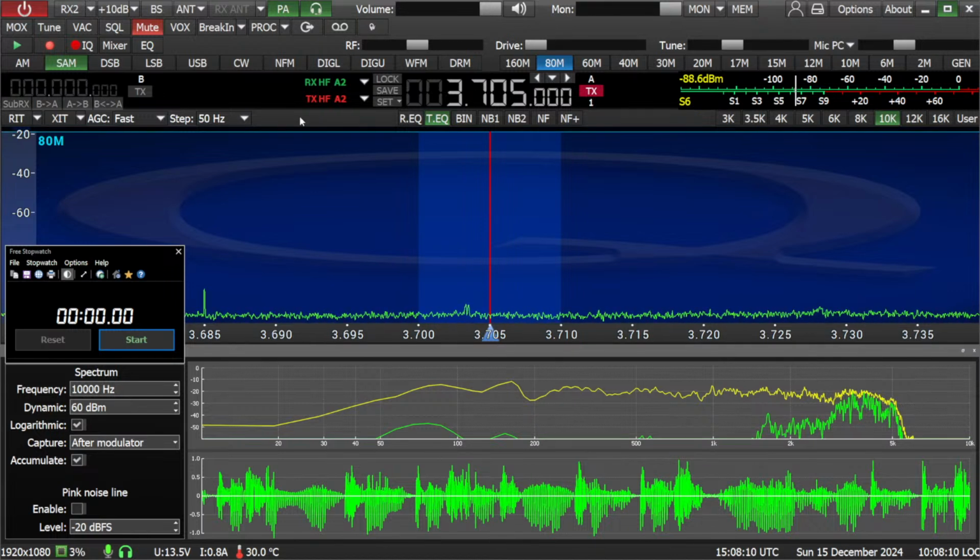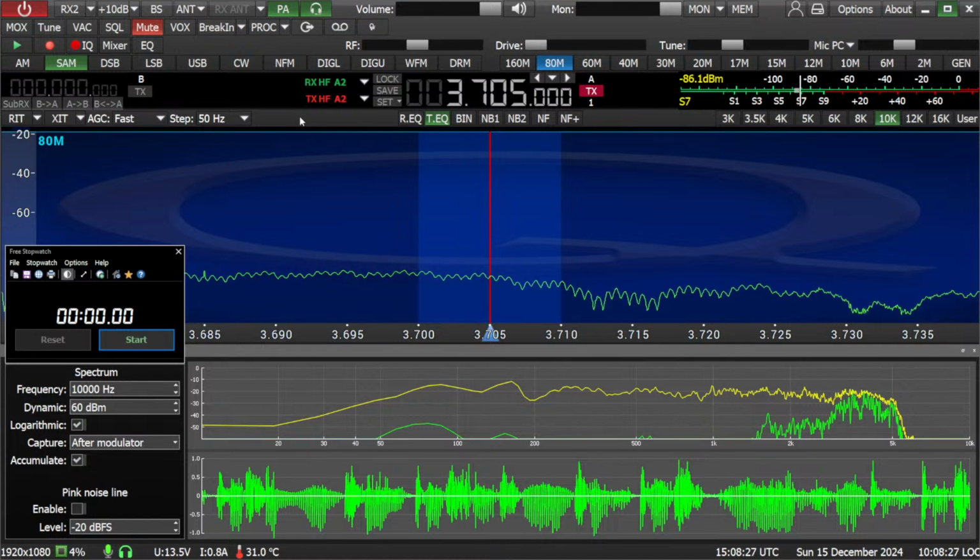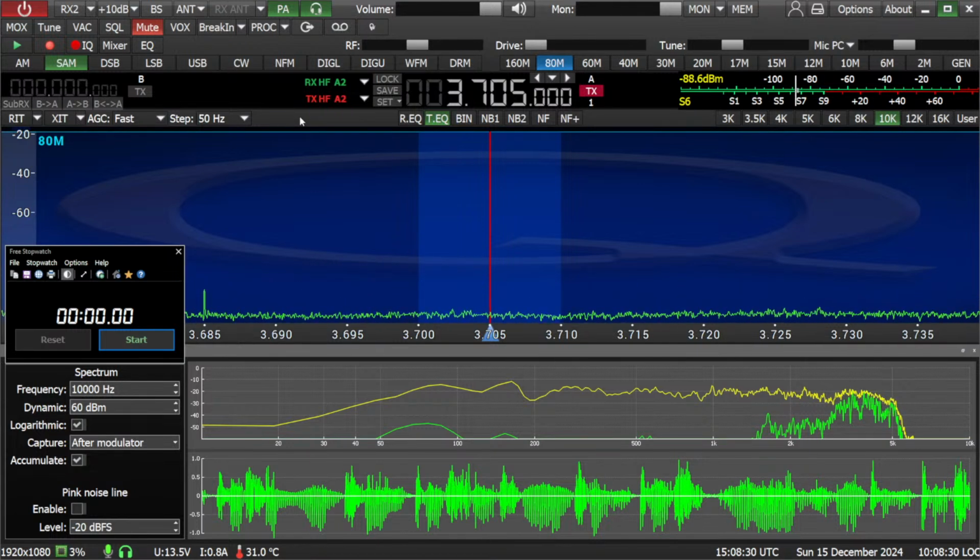What you'll end up with is a reverse swing where your carrier level drops. Now the way I have it set up is it's going the other way. So if I'm pushing, let's say, a 200 watt carrier with the ACOM 2000 Alpha, which I do every day, I see on the average on the watt meter a 200 watt carrier, and under modulation, I will see about 250 watts in the modulation. It's going in the right direction, right? If it goes in a direction at all.